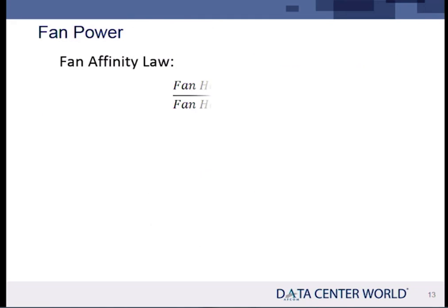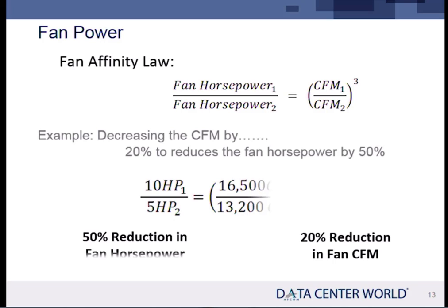Okay? So now the other thing to remember is the affinity law, or sometimes called the fan law, which is a well-known relationship as well. Specifically, the amount of energy required to drive a fan is related to the RPM of the fan cubed. In other words, the relationship is cubic. That's a big jump. So by reducing the amount of air going into the room, I get two benefits.